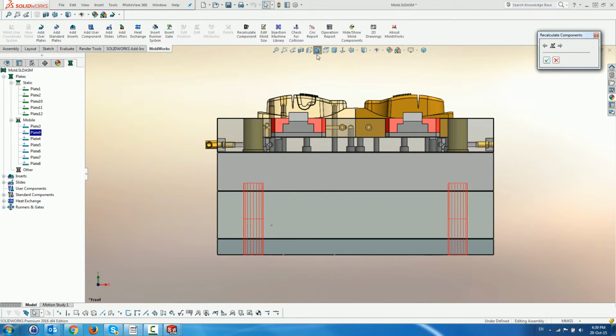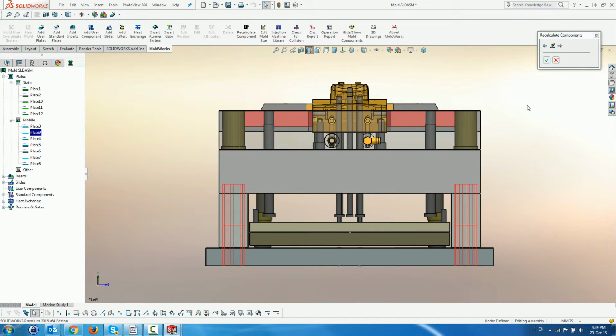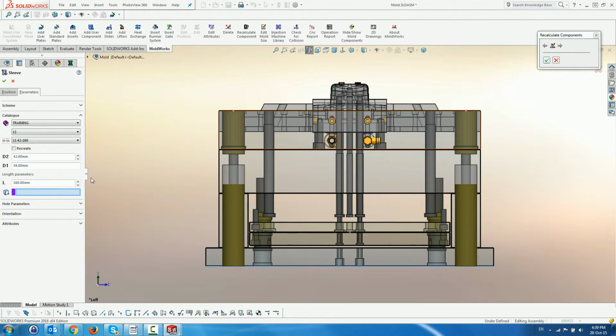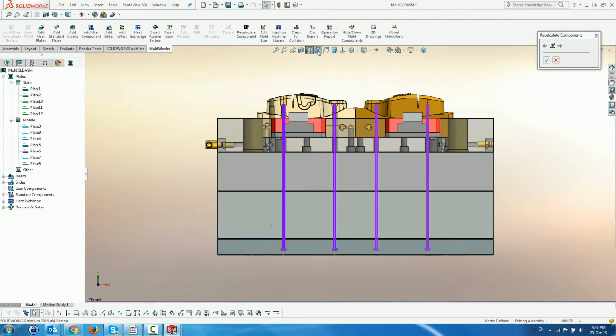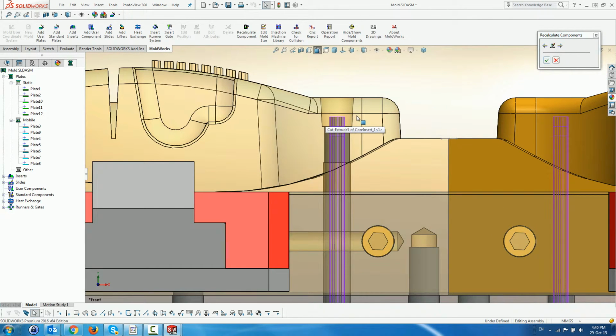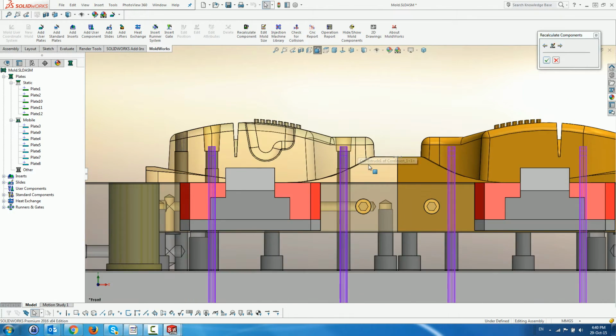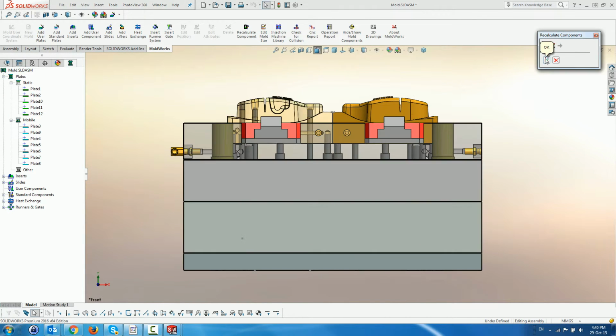At any stage, the component can be edited with the standard MoldWorks Edit Component menu. After making a necessary adjustment, we are returned to the Browse dialog. Notice that the ejectors have been automatically adjusted, i.e. lengthened to suit their functionality. Finally, we activate the process and the components are modified. The updated mold.